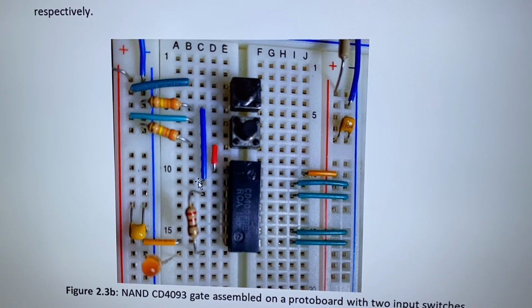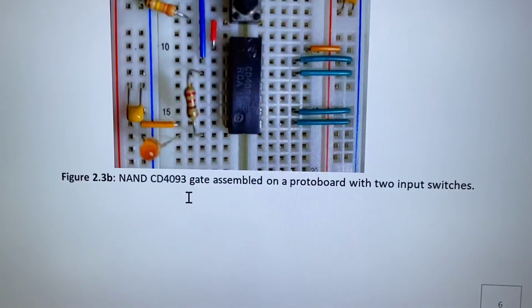You can test it. The inputs we're not using, like the Nand gates on the other side, you have to ground the unused input pins. Never ground an output pin, or you will have a short circuit, and it'll get damaged. These capacitors are bypass capacitors. They are used to reduce electrical noise from the gate. Okay, I will continue with other gates.